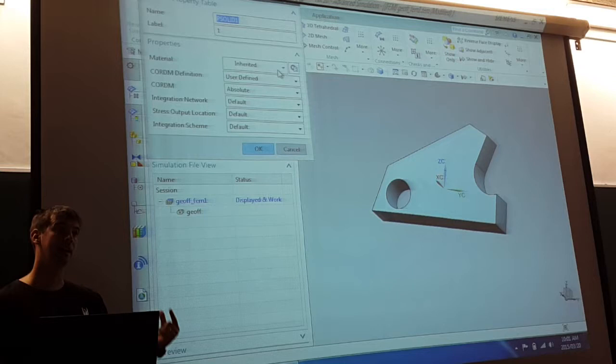You can look at super elements, you can look at flexible bodies, linear buckling, response simulation, which is a transient analysis, nonlinear statics, a modal frequency, modal transient response. There's lots of options available to you here. Alright. So what it has, at the moment, as a default, is perfectly fine, so we say OK.